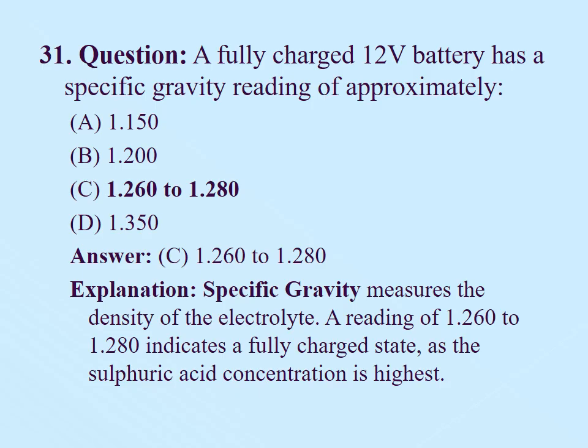Specific gravity measures the density of the electrolyte. A reading of 1.260 to 1.280 indicates a fully charged state as the sulfuric acid concentration is highest. Next question.